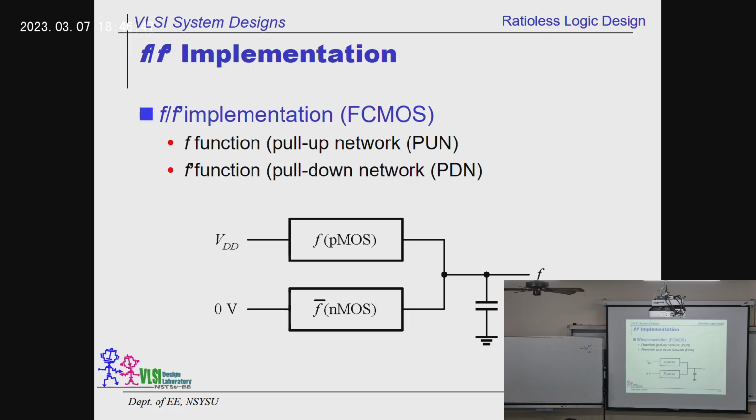Then we talked about one thing. If you're given a Boolean equation, step number 1 is to reverse it. Let's try this example. This is a NOR gate. Step number 1: we reverse it. We use G, which is the inverse of F. Then we have A plus B. We see that there is a plus. Plus stands for parallel.